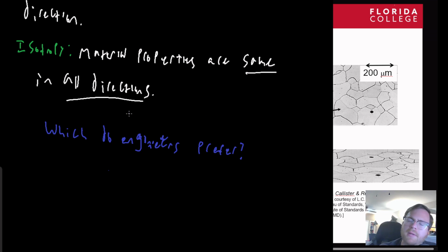That's usually what we prefer, but there are specific use cases like that turbine blade, and some other things you could probably think about, like really high performance vehicles, for example F1 racers, where you might want to use really expensive single crystal materials or anisotropic materials to make it work. In fact, most composites are actually anisotropic. Carbon fiber, for example, is highly anisotropic. Usually you can make carbon fiber isotropic, but that's a long discussion. But anyway, it's situational. The answer is it's situational.